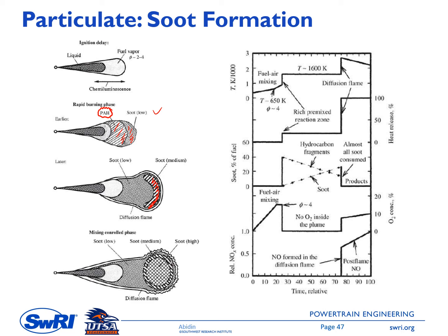We have a high soot formation at the middle or at the central zone of this spray, and then we also have the soot formation surrounding this high soot formation, and then at the very edge of this spray there will be a soot oxidation, somewhere here.